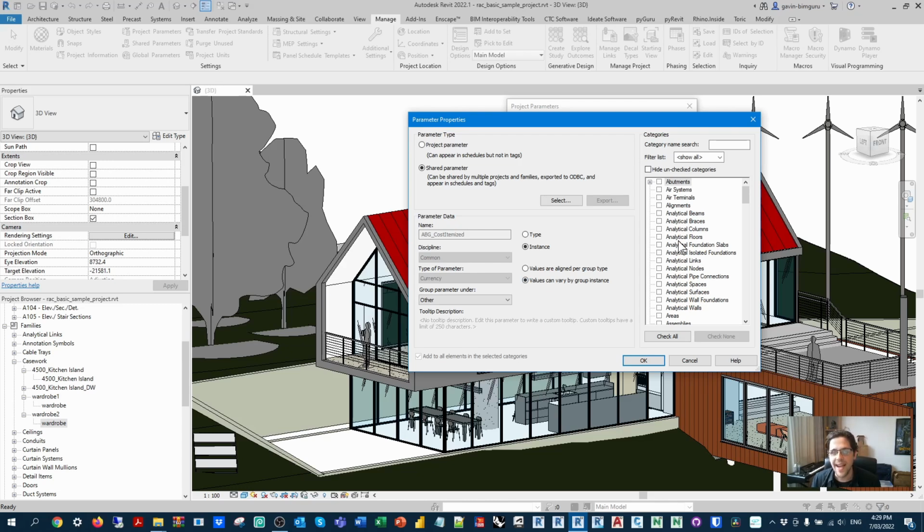And this is how much that actual object will cost. So I'm going to do check all, and in this case I'm just going to find anything that I know typically is going to have nested groups that we want to apply costs to on an individual basis. So handrails and rails, fascias, gutters, and soffits, and I believe that's all we need.